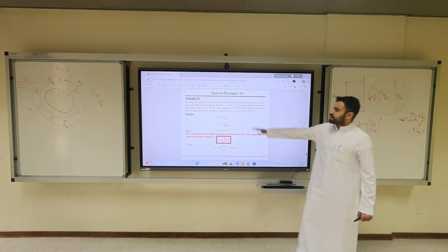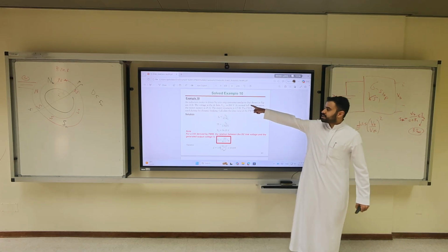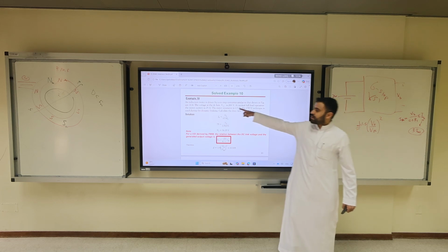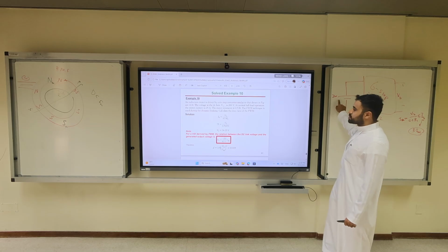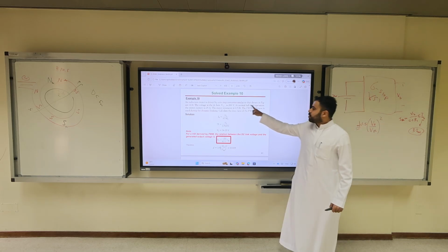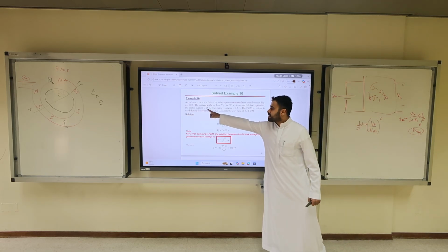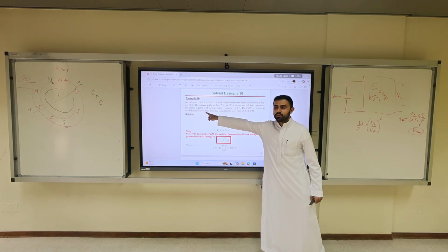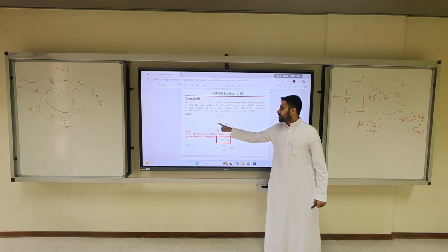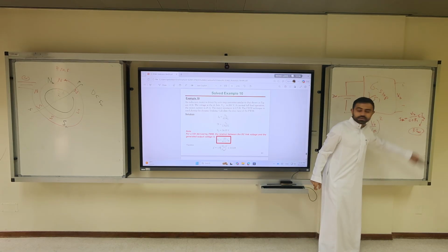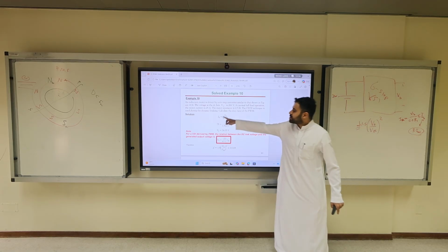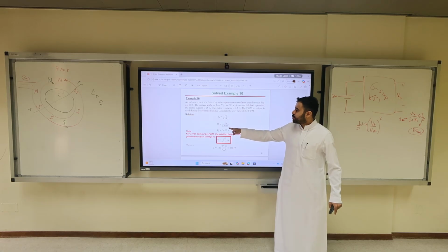Induction motor is driven by a 6-step converter similar to that shown in the figure. The voltage VDC is 200. At normal full load torque operation, the motor current is 25, so you are capped with what? 75. So IB is 75. It's 3 times IA. If you solve this equation and plug R of 0.5, you get VB of 56.